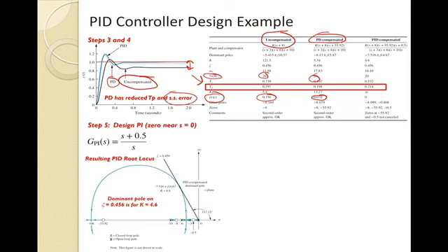So next, step 5, we want to design our PI controller, and here's the general form as you see here. So we have a pole now at 0 that we are introducing. And then we have some flexibility in terms of where we put that PI zero location. So I'm putting it next to the pole at 0 here. I've chosen -0.5. Again, you can vary that and see differences in the response, but that's where we've chosen it as of right now.